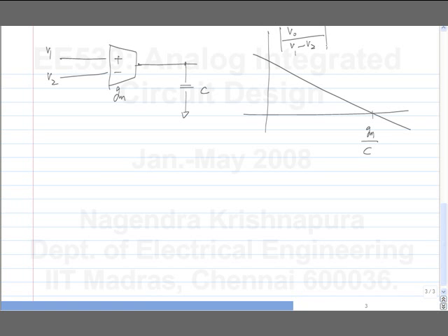Why would this circuit have a finite DC gain? What would make the circuit have a finite DC gain? Finite power supply. Why would that do that? We are talking about small signal incremental gain here. What's that? How much charge the capacitor can hold? Okay, what is the gain of this at DC? A constant current will flow through the capacitor and it will become infinite. So if it can't flow through the capacitor, you will have a finite DC gain.